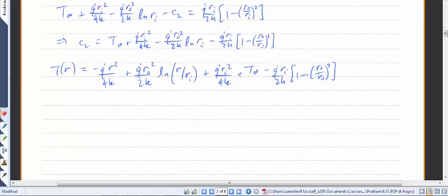So now that we have our general expression, we can find at what radius we'd have the maximum temperature for any point along the pipe. To do this, let's first take the derivative dT/dr and set it equal to 0. We already know that this should occur at the outer radius Ro, but we'll double check here to make sure.